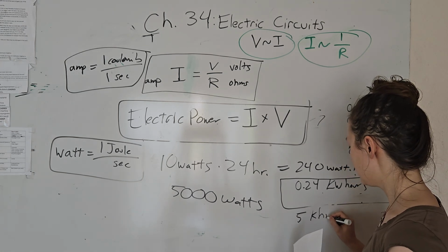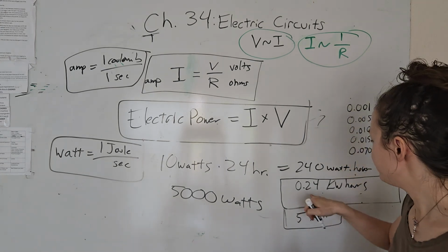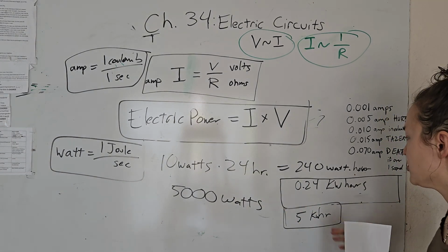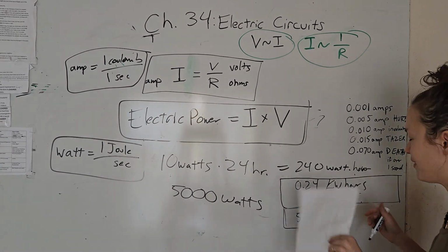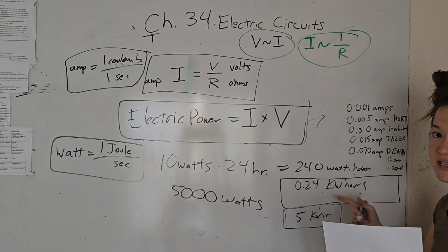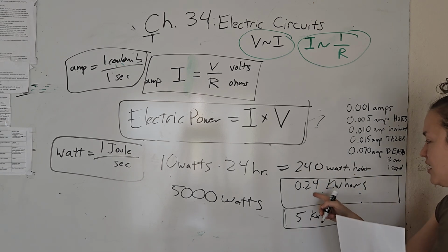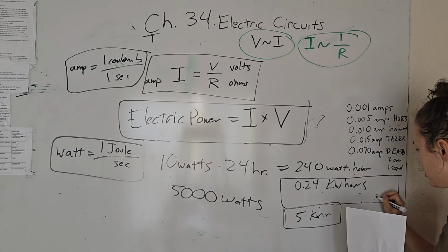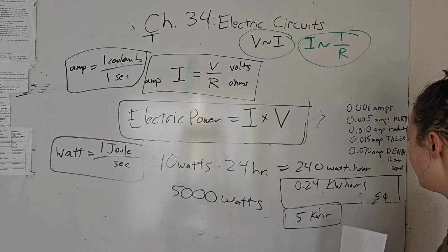So running the dryer for 1 hour uses 5 kilowatt hours, whereas putting on my 10 watt light for 24 hours only uses 1/4 of a kilowatt hour. Sorry, I was being dumb before. So with 14 cents a kilowatt hour, I only spent 1/4 of 14 cents leaving my LED 10 watt bulb on for 24 hours. So that's around 5 cents.